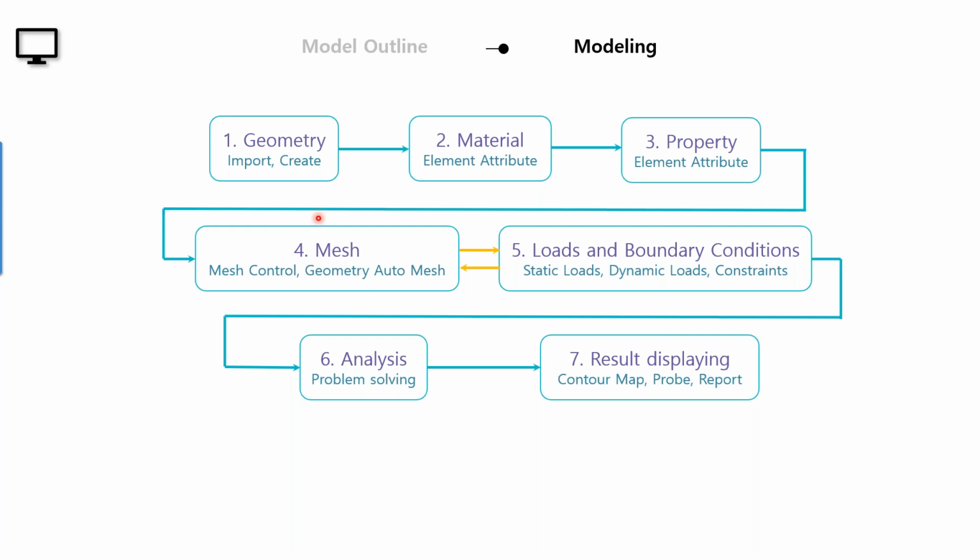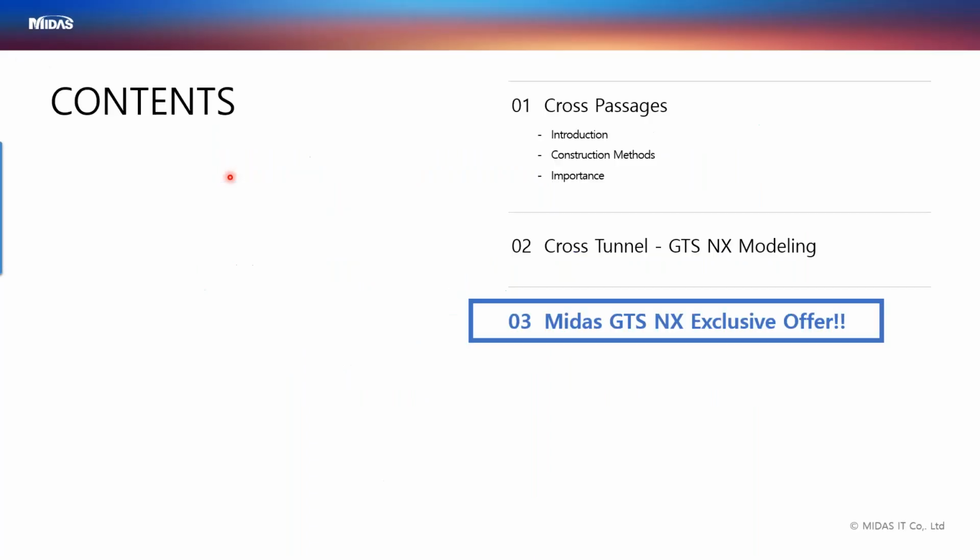And then we will mesh the entire geometry. We'll discretize the entire geometry to form a mesh. And then we'll be using the hybrid mesh here. So you'll have hexahedral elements, pyramid elements, pentahedral elements, which will make our life a little easy in terms of analysis time. And then we will apply the loads and boundary conditions, run the analysis, and get the results. So we'll interpret the results as well. That's the workflow. So let's start with the geometry. So yeah, let's start modeling.